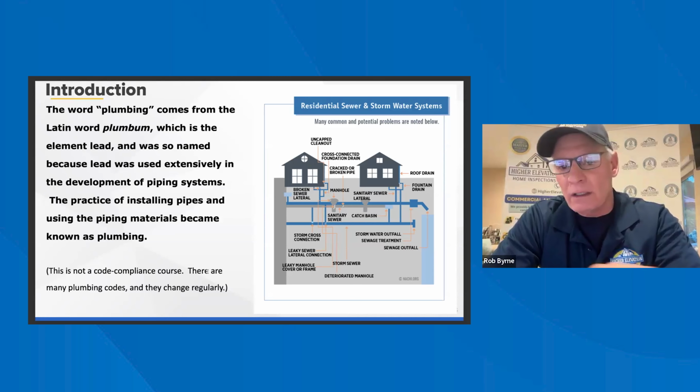Sometimes you will also see a burnt or corrosion on just the inside of one of these fittings. That would also be an indication we're backdrafting into the house. Now, looking here, we also need combustion. Whenever we have a furnace or a water heater, anything that burns gas, we need to have oxygen for the unit. When we're in proximity to the dryer,